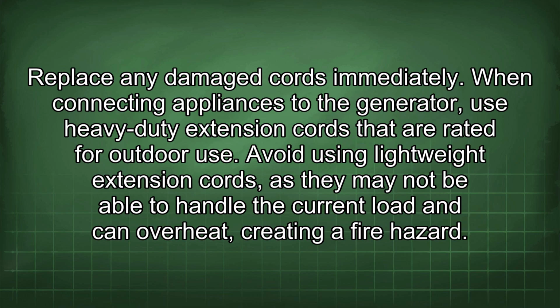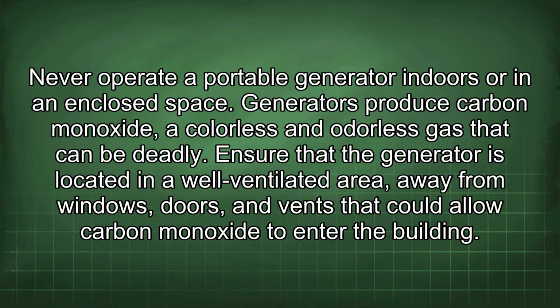When connecting appliances to the generator, use heavy-duty extension cords that are rated for outdoor use. Avoid using lightweight extension cords, as they may not be able to handle the current load and can overheat, creating a fire hazard. Never operate a portable generator indoors or in an enclosed space.